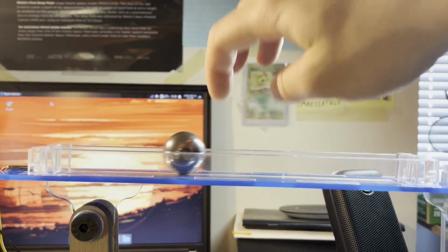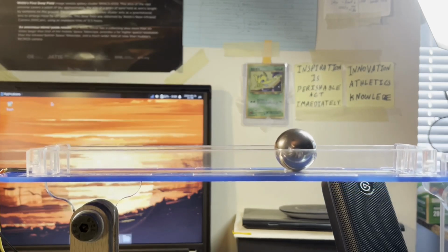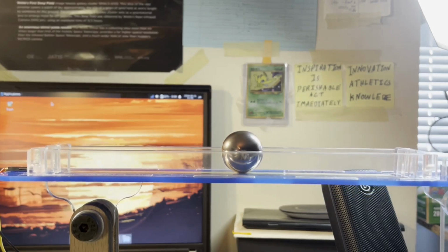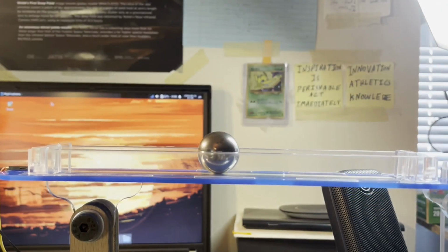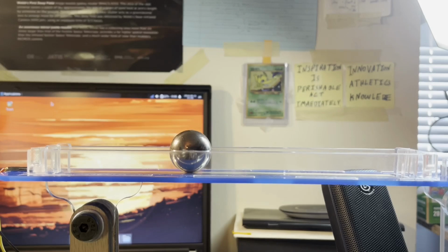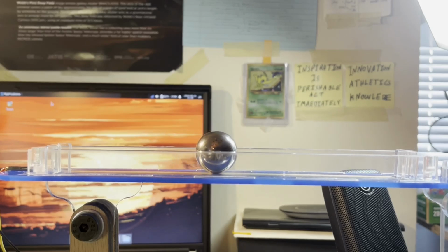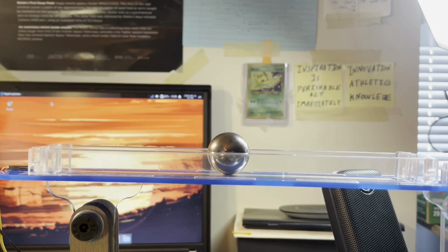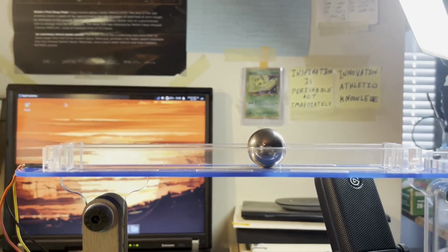Now there is a deadband, meaning that the ball could be considered balanced once it's plus or minus 1 centimeter within the set point. So the servo won't actually activate anymore once within the deadband. As you may have noticed, these small tweaks near the end are a consequence of the integration term.